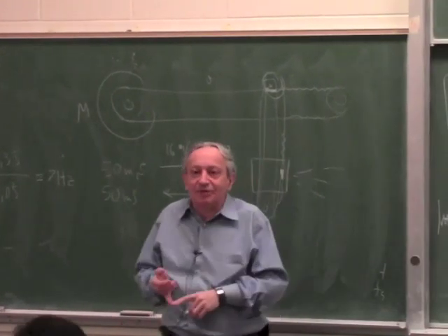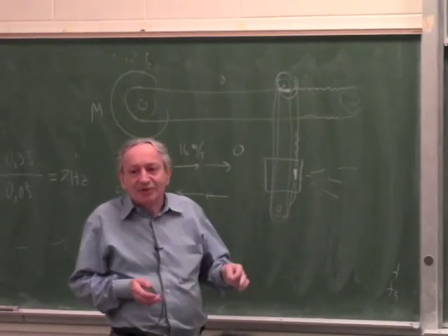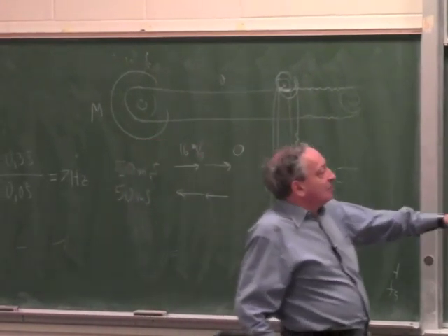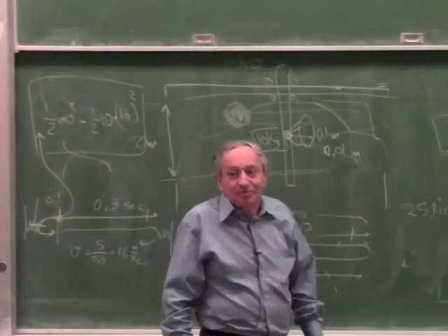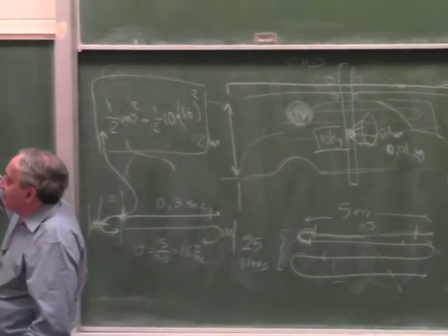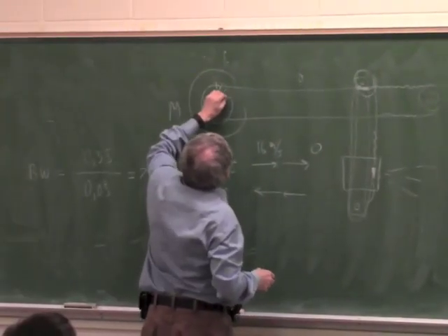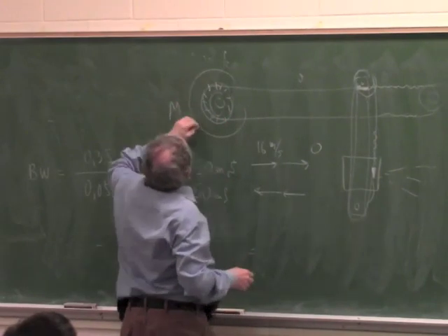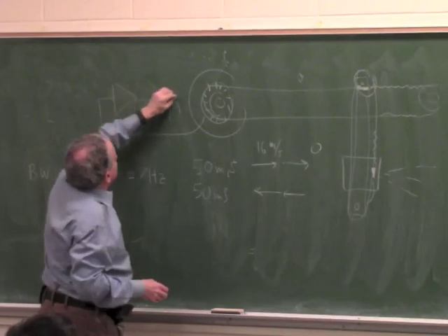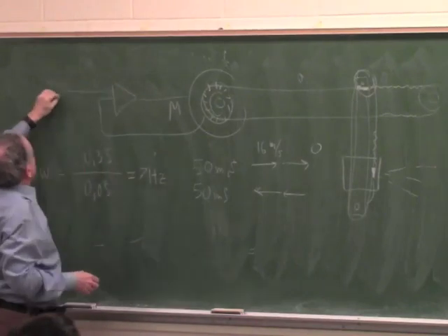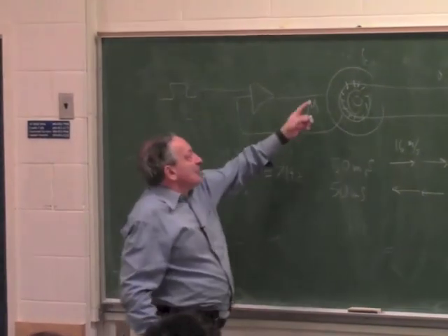So now we know the bandwidth, the power, the maximum forces, the speed. Accuracy is not a big deal here, because if accuracy, you need some kind of a sensor, because you need 1 centimeter. So this motor has to have some kind of a sensor, maybe a shaft encoder. Okay, and you have to run it closed loop. You have to run it through the shaft encoder to the motor, and here is a command. Because you can't just rely on an open loop motor.